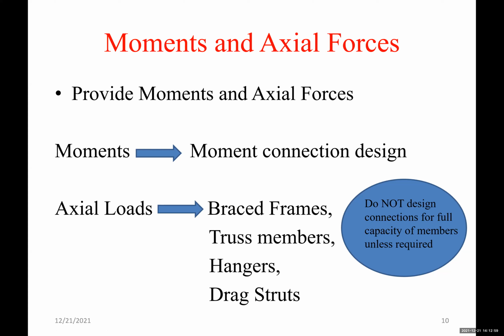Okay, moments and axial forces, this is similar to reactions. So here, same thing, provide moments and axial forces. Moments are used for moment connection design. So instead of designing for the full member capacity in moment, which is still done until today by many, many engineers, we can just design for the moment. That connection in a moment frame has a moment on it. So provide that moment and let them design for that. If it's a bolted connection, it will result in much fewer bolts. If it's a welded connection, it will result also in smaller weld sizes and lengths. And also the plates, if we're using plates at the top and the bottom of the beam for the moment connections, we will have thinner plates than the thicker plates that are used for the full moment strength of the members.